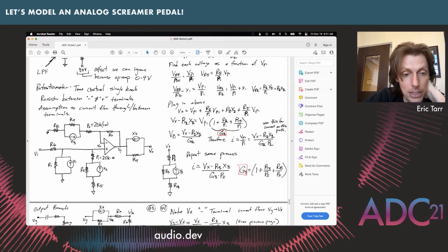So this is the potentiometer that's split, and then it goes into the capacitor, and then into another resistor. And I duplicate this, but I have the opposite wiper value up here. When we go the other direction, my potentiometer I've just called alpha, and it goes through that potentiometer, then through a capacitor, and then through the resistor down here. And so that's how I'm dealing with that particular potentiometer.